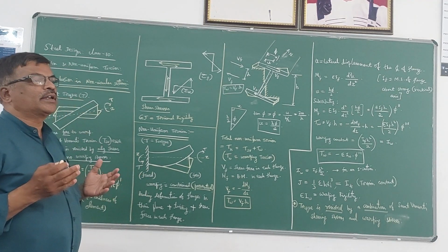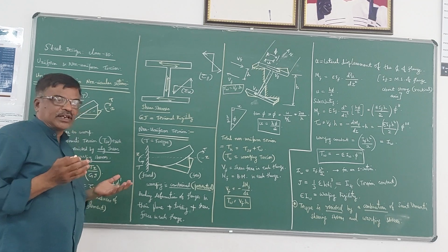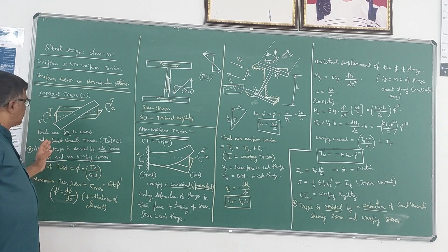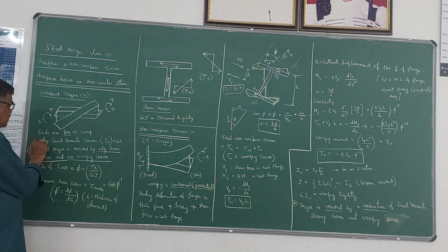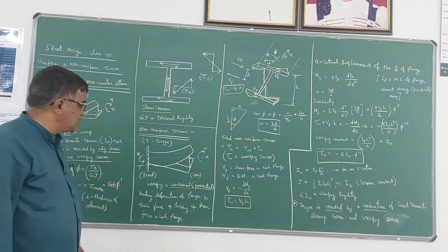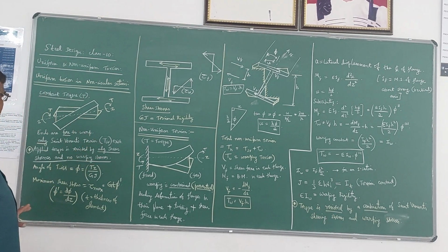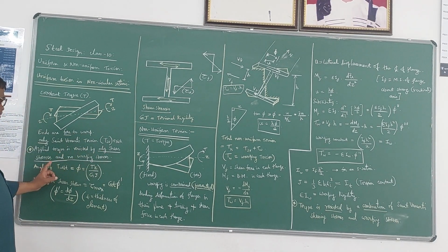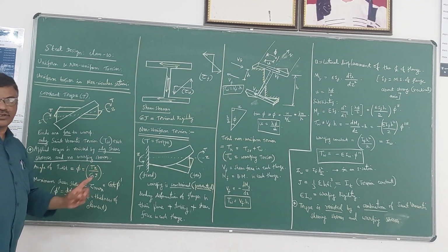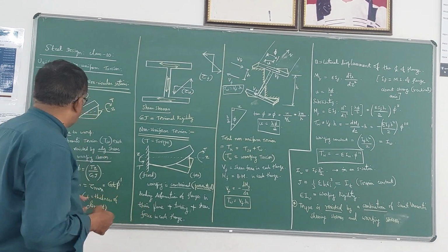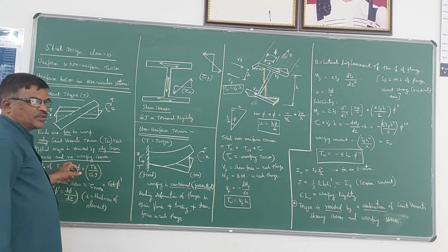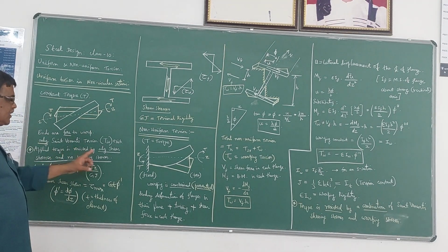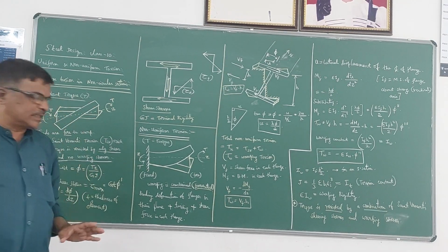So you have studied in strength of materials, the torsion theory, plane sections remain plane even after twisting. That concept holds good here. So only Saint Venant's torsion, pure torsion, called TSV, exists in this case. And another thing is the applied torque T is resisted by only shear stresses and there are no warping stresses. Out of plane deformation is called warping. So there will not be any warping stresses in the case of both the ends free. The torque is resisted by only shear stress.